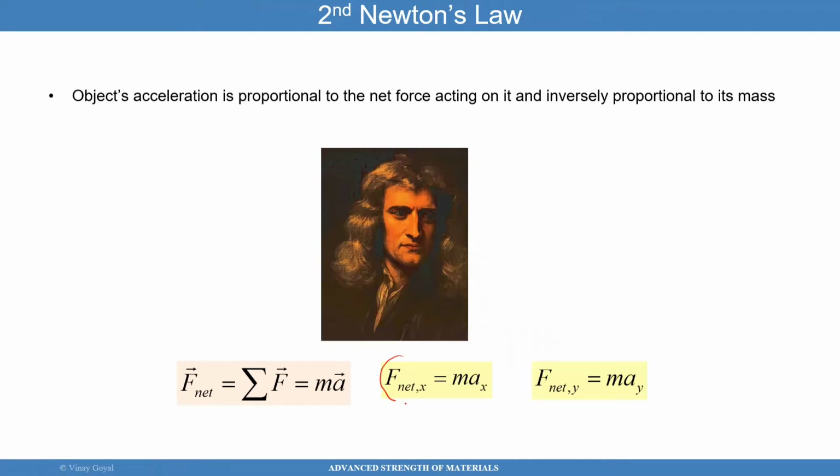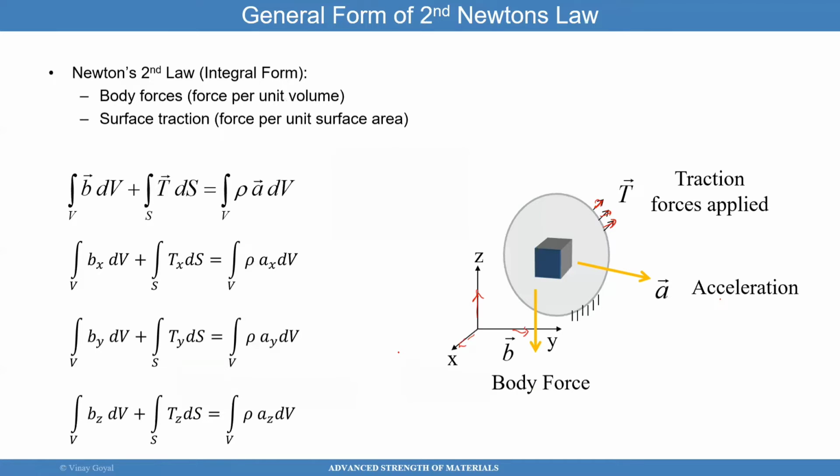on the left-hand side, we're talking about this, is equal to mass times acceleration. So here I have acceleration times density. So this acceleration can be decomposed into the x, y, and z. So I look at the x component of acceleration multiplied by density, multiplied by that differential volume, but also sum it all over the place in that body. If I do that in the x, y, and z direction, I get three equations.